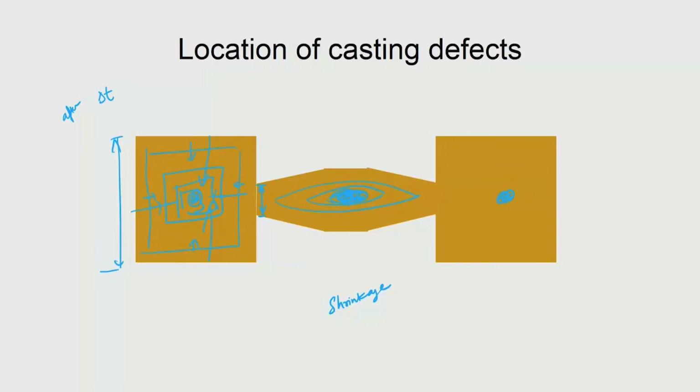So, the way to fix, for example, in this situation would be first to avoid this kind of a curvature. So, you have a curvature this way and later on you can machine it. So, that is the first thing that you would do, and of course, you would have, for example, a riser with some hot mixture, hot top, okay, so that the last to solidify liquid would be somewhere here and not here, and therefore, you can avoid the porosity or shrinkage defects at the center.